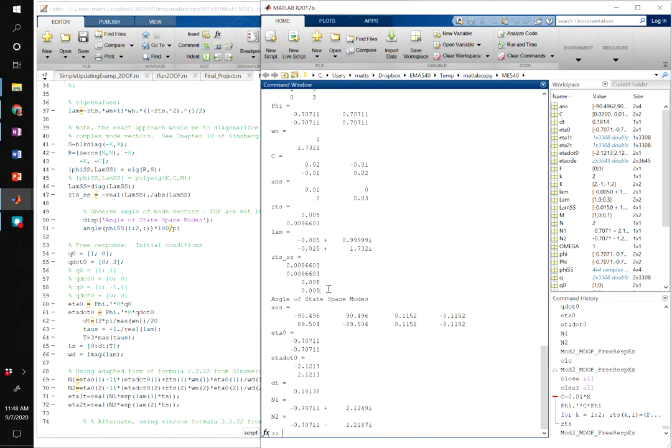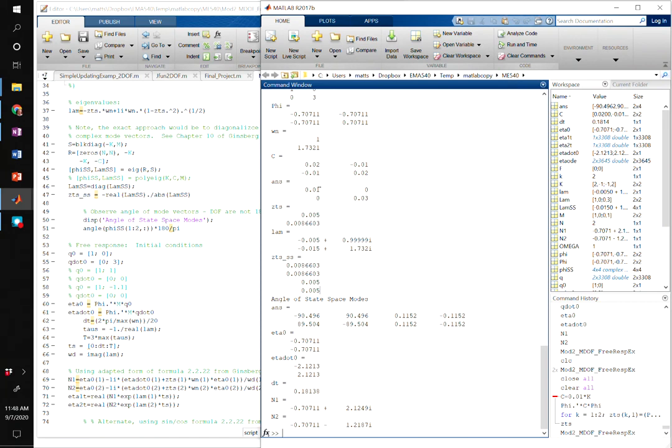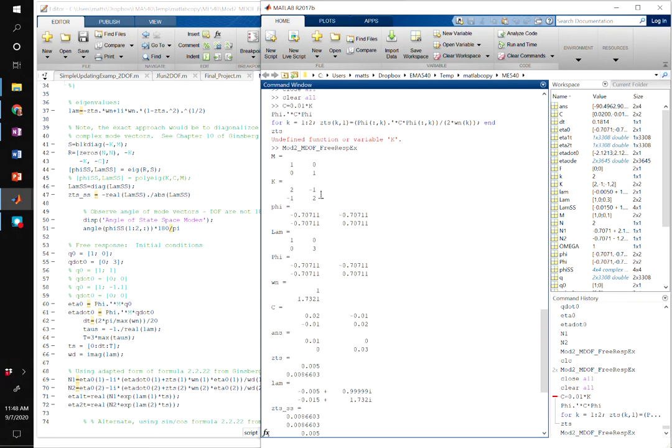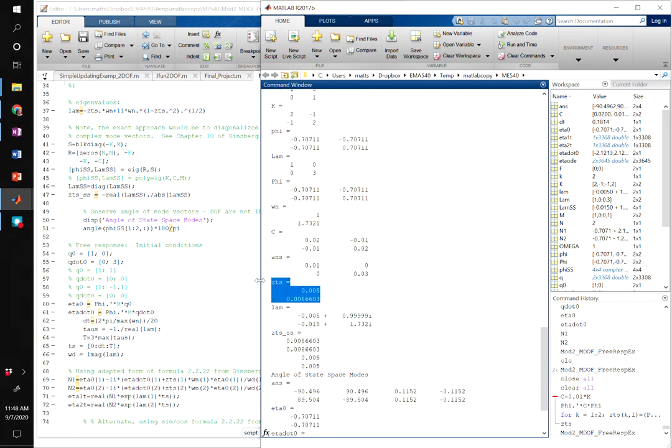And so we get these eigenvalues, and notice the ordering comes out differently, but they are the exact same as the ones that we calculated using the formula above for the case where the system is proportionally damped, where this phi transpose C phi came out diagonal. So the classical damping, or the damping we get using the approximation in this class, is the same as the state space. There's two eigenvalues, one for the positive I and one for minus I.